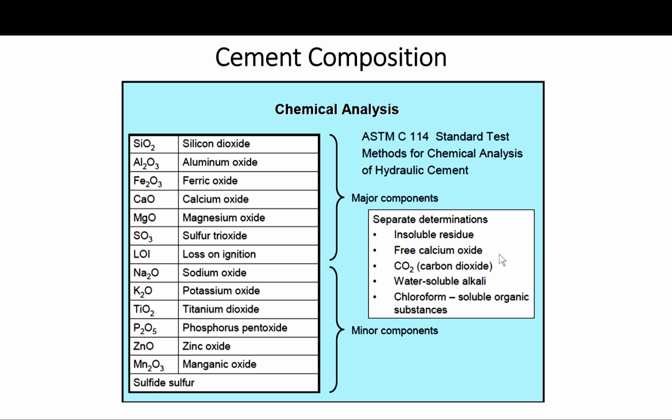This one, of course, we will go over. For quality control purposes in the cement industry, the fineness is easily determined as the residue on standard sieves, such as the number 200 mesh, the 75 micron, or the number 325, which is the 45 micron. It is generally agreed that cement particles larger than 45 micron are slow to hydrate, and those larger than 75 may never hydrate completely. So particle size distribution is important.